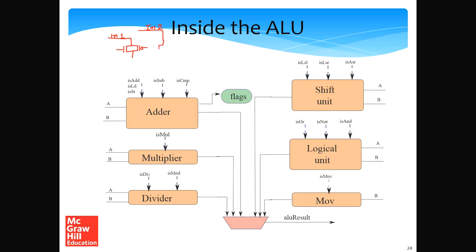So let's have two transistors back to back, and let this be the output line. Let the signal that's controlling this be A, and let this be the complement of A, which means both are enabled. Similarly, let this be B and the complement of B. So this structure over here is called a transmission gate.